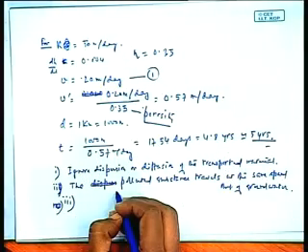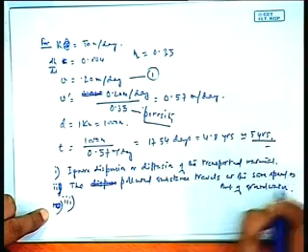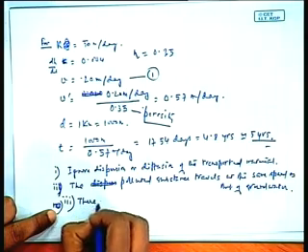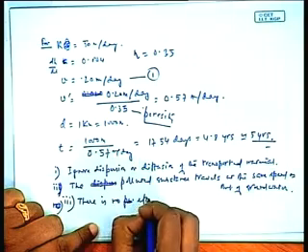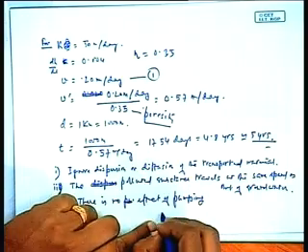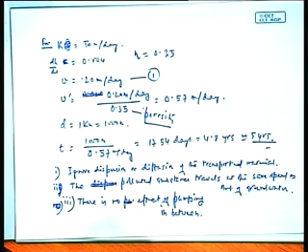When you consider it perfectly mixed, then you can consider that the polluted substance travels at the same speed as the groundwater. And the third is that there is no effect of pumping in between, in between the two holes under consideration, the two points that we are discussing.